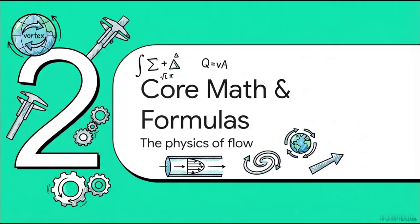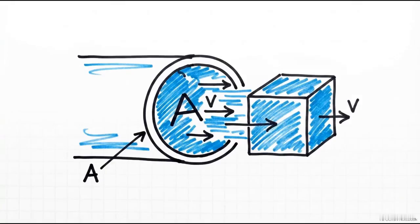Section 2, Core Math and Formulas. Let's look at the foundational physics that actually make this possible. Everything kicks off with the continuity equation. Q equals A times V. It looks simple, and honestly, logically, it is. The amount of fluid flowing through a system, that's Q, our volumetric flow rate, simply equals the cross-sectional size of the pipe, A, multiplied by how fast the fluid is moving, which is V, our velocity. So if you shrink the pipe area, the fluid has to speed up to maintain that same flow rate.